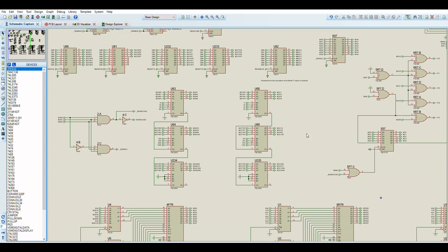This basically takes a 4-bit value and adds it to the 9 and 8-bit value for the horizontal and vertical pixel position. With the relevant carries, this accounts for the upper bits that need to carry through properly.